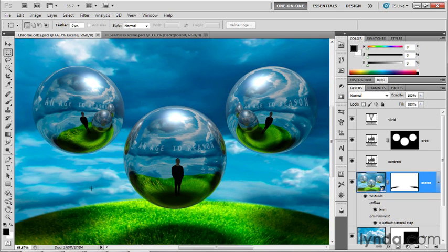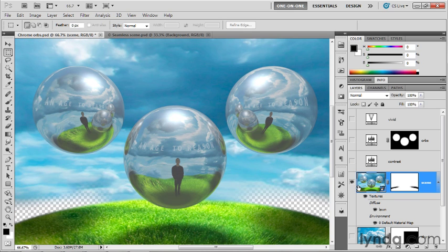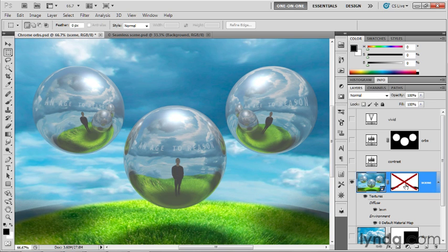Now, the larger scene around us is a 4th mesh that's known as a spherical panorama, and there's this big sky and grass scene that's wrapped inside of that sphere. And let me show you what I'm talking about. I'm going to turn off everything but the 3D layer by Alt-clicking or Option-clicking on the eyeball in front of the scene layer here in the Layers panel. And I'm also going to turn off the layer mask by Shift-clicking on that layer mask there. The layer mask, by the way, is responsible for curtailing these aberrant masks that are cast upon the ground plane.